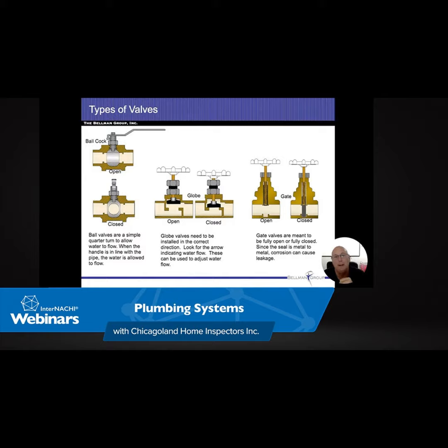So hot on the left, cold on the right. We want to have a pressure relief valve on it. Pressure relief valves, numbers that you should be aware of: they're designed to open up and stay open, and we'll show that picture in a little bit, at somewhere around 210 degrees. They're also designed to open at 150 psi of pressure.